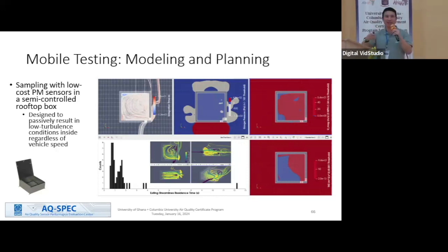But I've done some modeling of that kind of idea, and there are non-ideal conditions of the turbulence and the flows going through. So, I'm starting to go to this kind of solution where you have a hole in the front of the box and then a hole at the side of the box. So, inlet, and then on the side an outlet. And that's because I'm trying to capture a low pressure area here to take advantage of, to draw flow in and draw flow out.